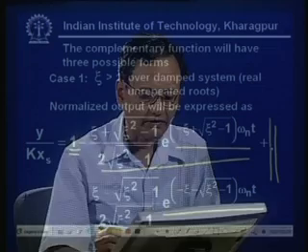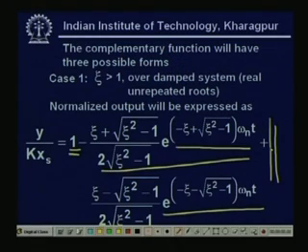Some systems are very sluggish, but if it is allowed that within 5% of the final steady state value it reaches, it will take some action, because in instrumentation, whether you are measuring temperature, pressure or flow, ultimately you have to utilize this to control some final control element, which mostly are valves or heaters which will heat the system, or boiler temperature. So this is very important.